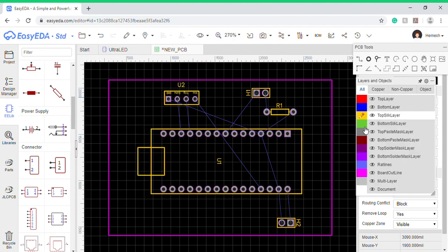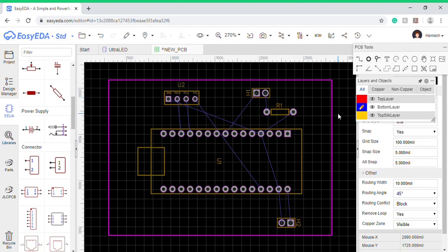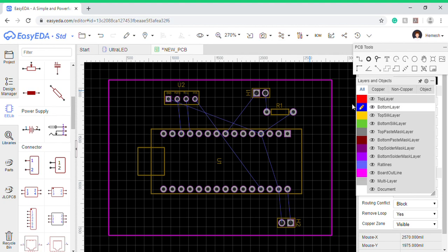So a PCB in our case, which uses through hole components with headers, we basically need the bottom layer. We basically use the bottom layer. If the wiring in the bottom layer is not enough, if there's not enough space for more wiring, you can use the top layer too.